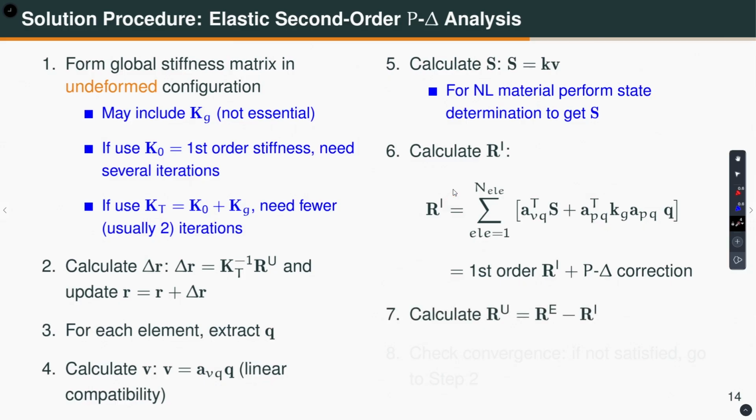So, now what do you have to do? Well, this external force vector is not shown here, but you know from before that the external force vector will naturally not be in equilibrium with Ri. So, Re minus Ri is my unbalanced force vector. Okay. So, what you do? You check for convergence using the criteria that we have discussed earlier in the introduction chapter, right.